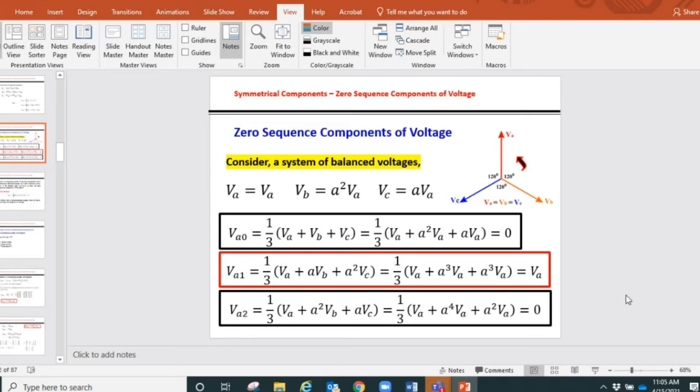And this also shows how the symmetrical component theory given by Fortescue is applicable and justifies what we have been doing since the beginning with three-phase voltages, not worrying or knowing about negative sequence voltage and zero sequence voltage, only using one voltage of phase A, and this phase A is also equal to phase B, phase C. Is that clear?